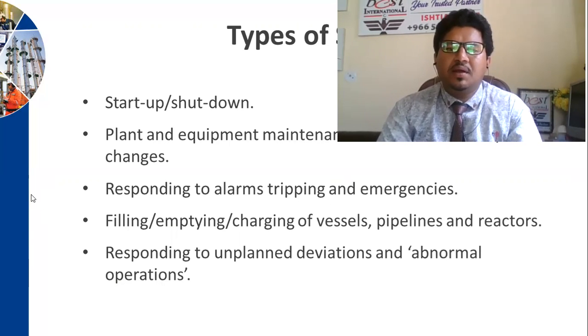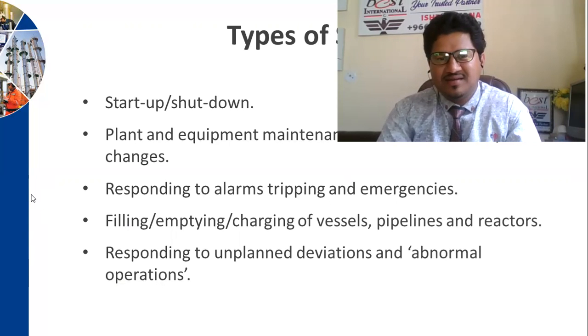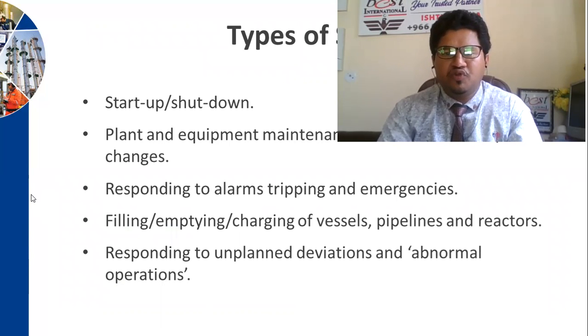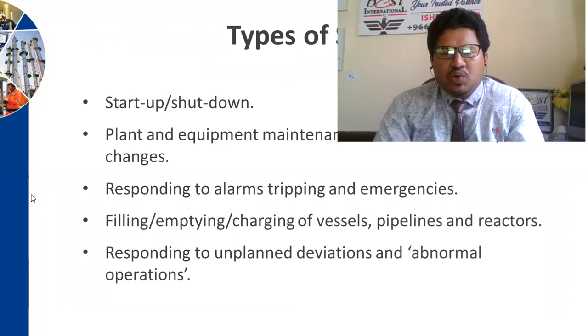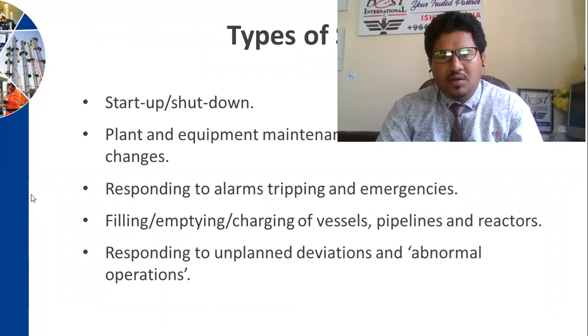It is also good to prepare an SOP for isolation or lockout tagout, or maybe separate SOPs on how to isolate, an SOP for disconnection and blinding, or an SOP for electrical lockout tagout or mechanical energy lockout tagout. So different kinds of SOPs must be established, and they must be easy to understand for the concerned technicians or manpower. And they must follow each step always, every time.